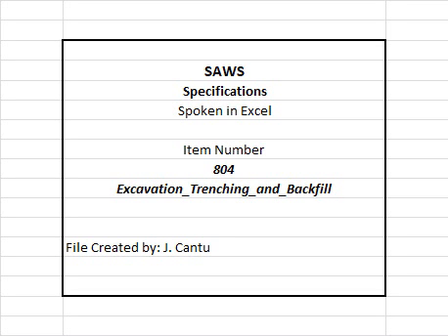accredited, independent testing laboratory for his guidance and control of the work. A. The owner will determine in-place density and moisture content by any one or combination of the following methods. 1. TXDOT Tex 113E, Laboratory Compaction Characteristics and Moisture Density Relationship of Base Materials. 2. TXDOT Tex 114E, Laboratory Compaction Characteristics and Moisture Density Relationship of Subgrade, Embankment Soils, and Backfill Material.